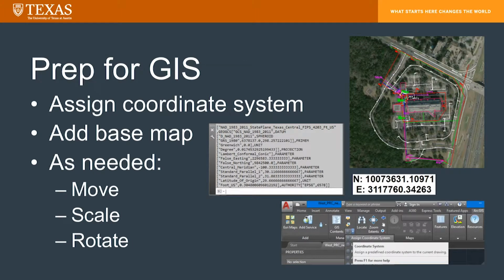Then you already know automatically that your DWG file is not assigned a coordinate system. One of the indicators for us would be if our DWG file were somewhere in this range of X and Ys. Then we would know, okay, this data is most likely already in a coordinate system, so I can probably go ahead and start the export from CAD to GIS.